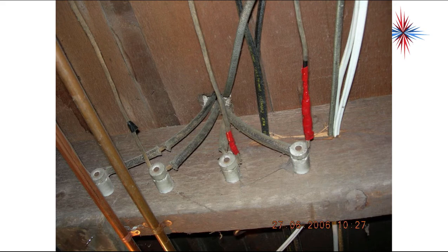From point to point, this uninsulated wire would just be stretched. Okay, when it needed to make turns or needed support, it would go into the knob that would be tightened down on top of it. If it had to go through a penetration, it would be put into a sleeve, which is the tube, and would be going through the penetrations. Again, old wiring, do not use it.